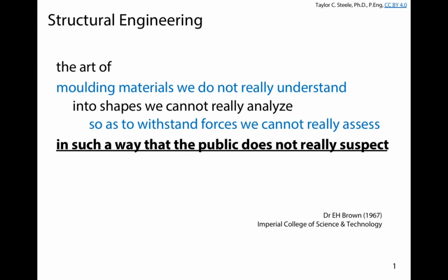We talked about braced frame systems and how we might experience lateral forces from wind, from earthquake shaking, and there's also a destabilizing effect from gravity loads that we consider through this application of an imaginary load called notional lateral loads. And so we kind of understand, or at least we've explored, the types of loads acting on structures, how those loads work their way through the structure, so we might be able to get the bending moment on a joist from dead, live, or snow, the axial force on a brace from wind, earthquake, and also from the effects of the gravity loads present in the structure.